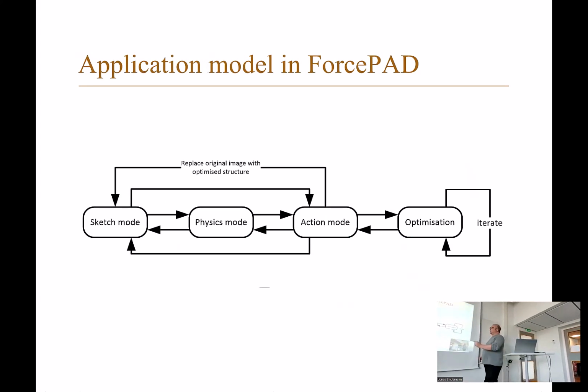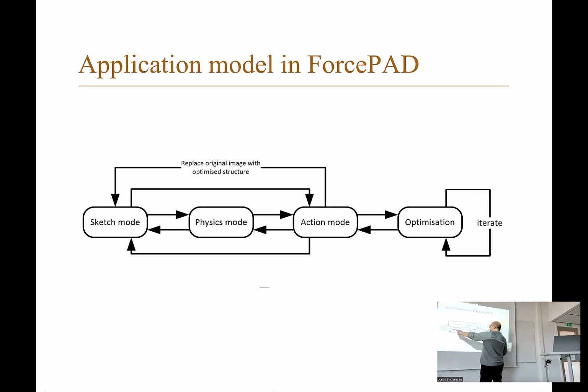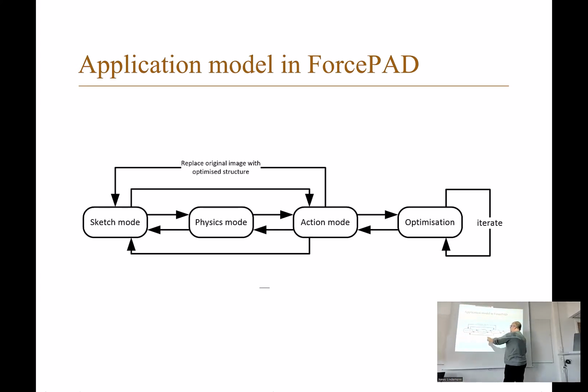And this is the way you have 3 modes. Sketch mode, where you draw, physics mode, where you add the constraints and forces, and action mode, where you actually do the simulation. And then we have a 4th mode that is outside here for optimization.